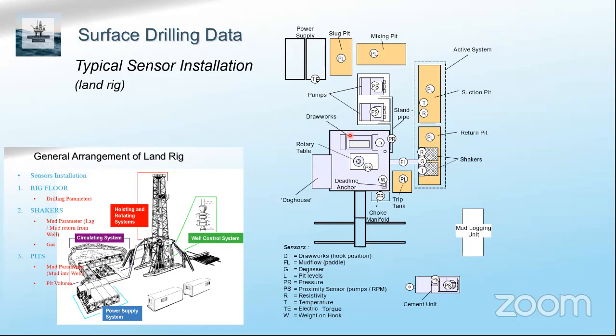Without this sensor, you cannot get the rate of penetration and many other things. You cannot know the depth and so on. So it's very important while drilling, or any kind of operation. In the very early days, without these sensors, they used to do kelly marking. But nowadays nobody's doing that. It was purely manual.